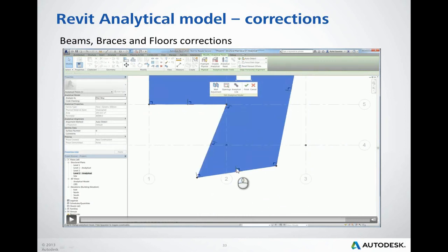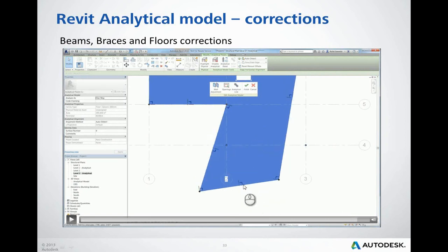And now clicking on the one direction axis, in this case the axis perpendicular to this indicated edge, allows us just to move along the selected direction. So now I will click on the second direction and it only allows me to move the whole edge in this direction.